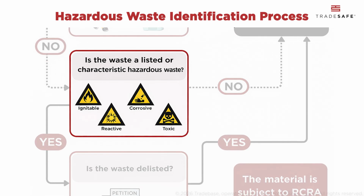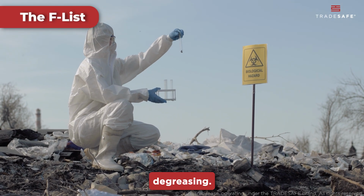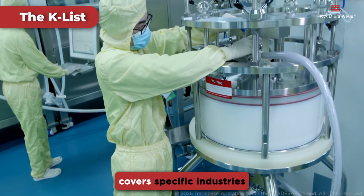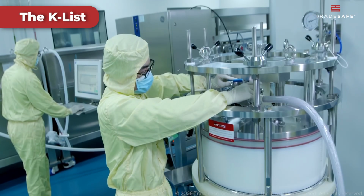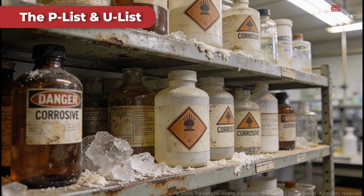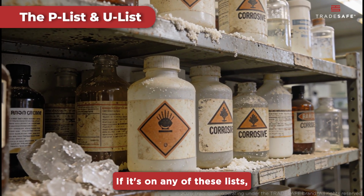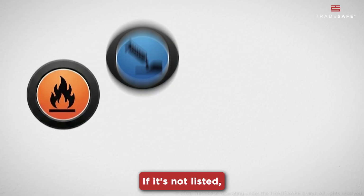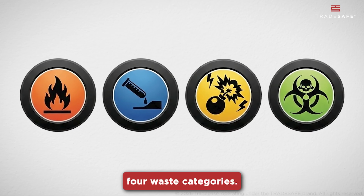In Step 3, professionals check if the waste is hazardous by determining if it's listed by the EPA or shows hazardous characteristics. The F list includes waste from general processes like degreasing. The K list covers specific industries like petroleum or pesticide manufacturing. Lastly, the P list and U list include discarded commercial chemicals. If it's on any of these lists, it's hazardous. If it's not listed, they check if the material falls into one of these 4 waste categories.